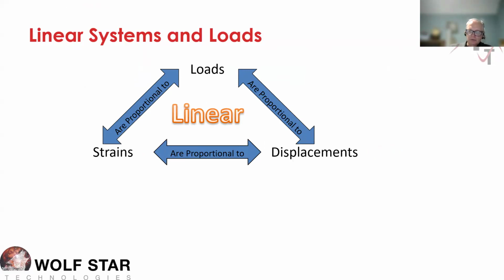But what we're doing is turning your part into a load transducer. So we're going to target nominal areas on your part where the strain response remains linear and proportional to the exterior loads. We're going to stay away from high strain gradient areas like welds or bolted joints or areas of contact.